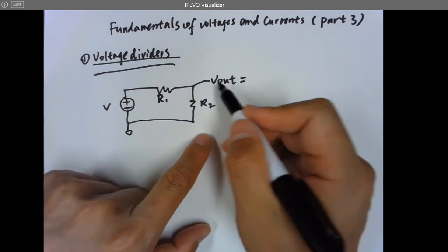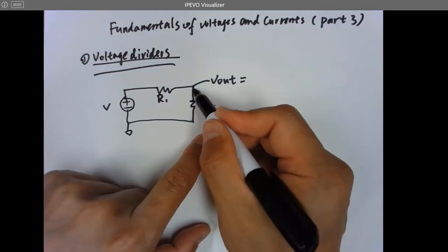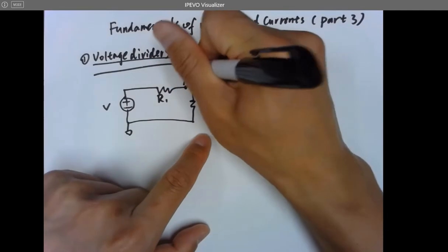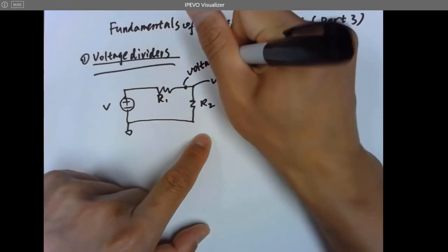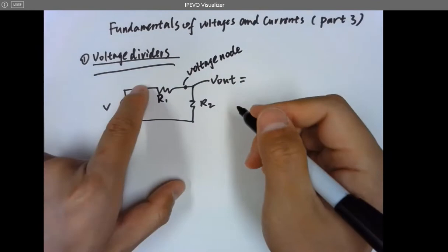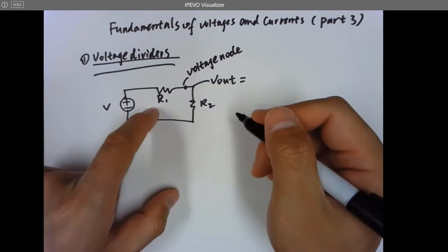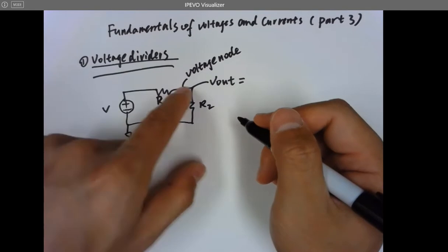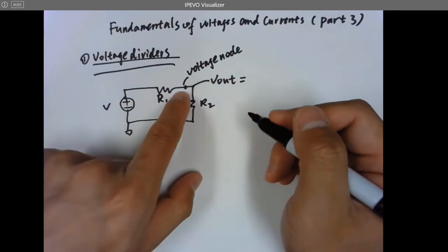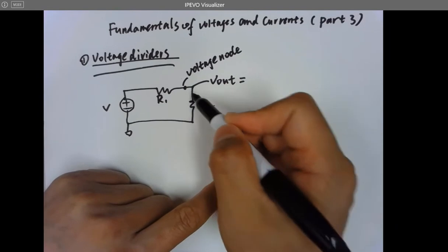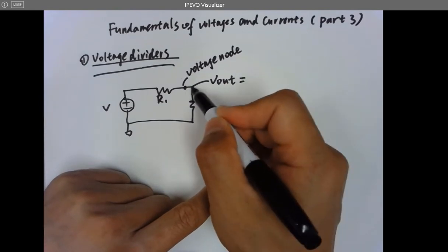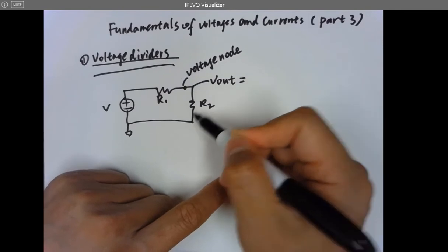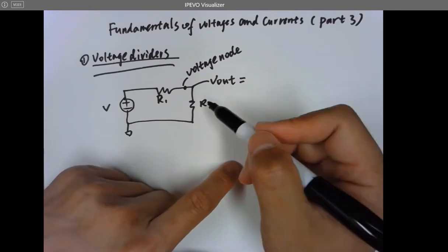Whenever we just point to a voltage node in the circuit, okay, so this is a voltage node, right? That's a node, that's another node. You have a total of 3 nodes in this circuit: node 1, node 2, node 3, because they have different voltages. If I just point to this voltage node, I say the voltage here is called VL. I'm comparing this node to the ground. So that's how that works.